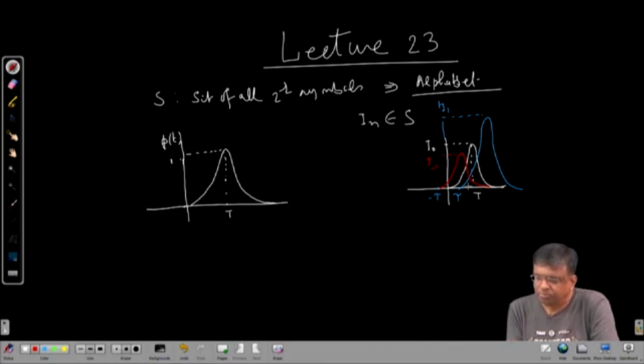and at the receiver I first measure the height of the waveform amplitude at T, assuming I get I0, then at tau time later, at T plus tau, I measure again, I expect to get I1, or at minus tau, I sample again, I expect to get I minus 1. So I0 at T, I1 at T plus tau, I minus 1 at T minus tau, tau to the left, because tau is the symbol period. Capital T is the peak of one pulse.